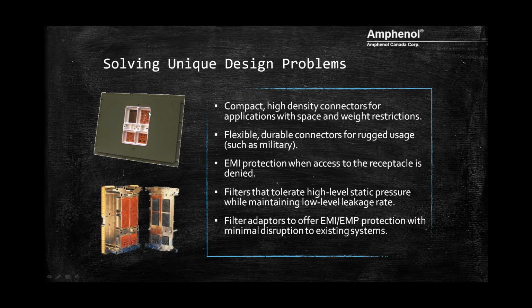Now, here at Amphenol, we have our own testing facility. All the connectors are tested. Each filter is tested for DWV, IR, and capacitance, your insulation resistance and capacitance, and we also look at the attenuation for each of the connectors at the various different capacitance types. A sample size is taken.